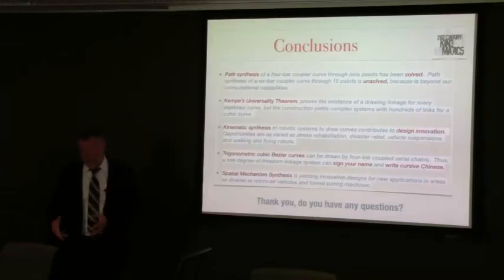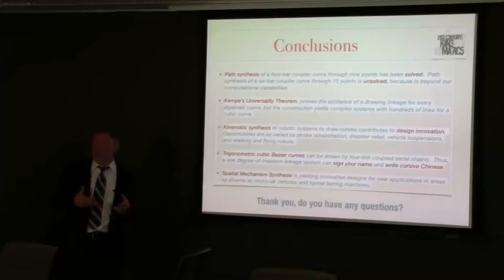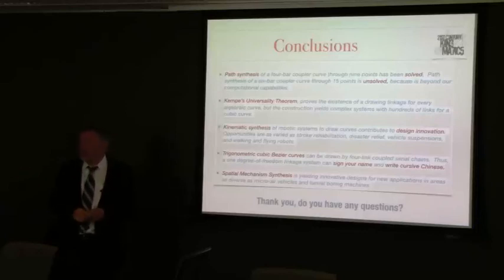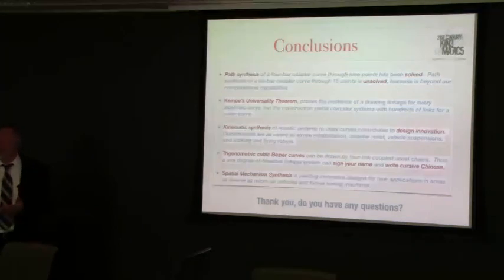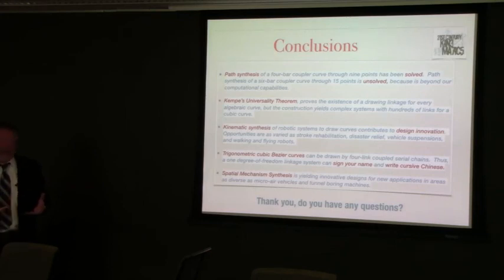We took that linkage and put it in an optimizer, because I can now take the same curve and just adjust it slightly. It turned out that it was a very small adjustment of 2 of the dimensions. Actually, it was a small adjustment of the placement of a fixed pivot that corrected that. So there is a surprising amount of room for getting more versatile devices by adjusting the devices that we design. And we haven't even had a chance to explore that.